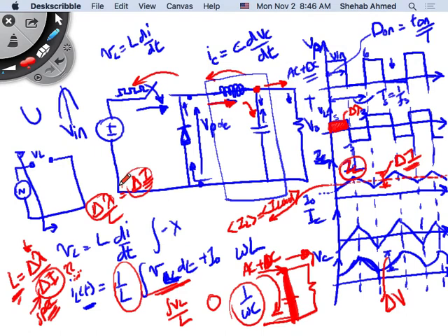So increasing the switching frequency allows you to use smaller reactive elements to deliver the same amount of energy, maintaining the same ripple. Or if you maintain the reactive elements, then to decrease ripple, you can increase switching frequency. It's directly proportional.